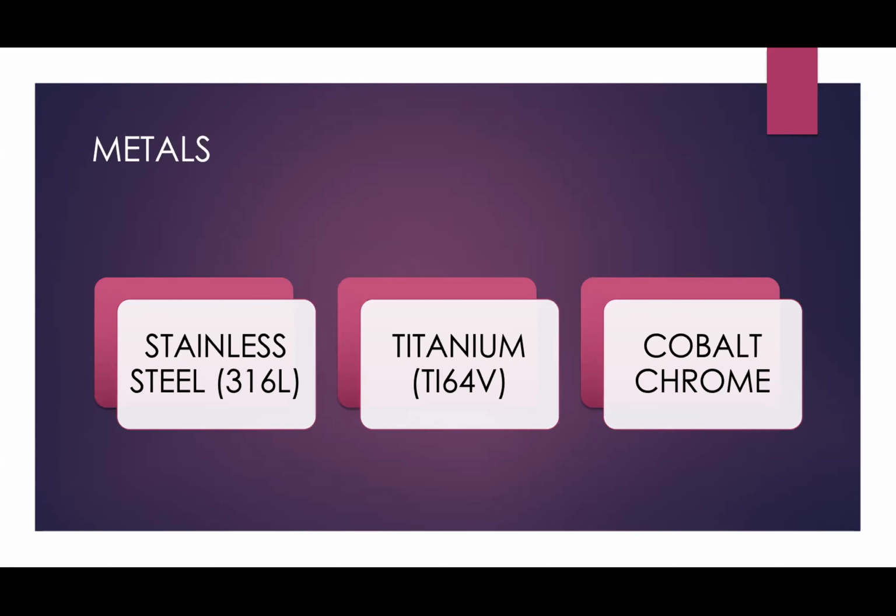It's biocompatible, but the downside is it's very sensitive to notches. It's got terrible notch sensitivity properties, which means if you sustain a crack, it will wear away very quickly. It's got terrible wear properties, so it's not good as a bearing surface, and it also gives off vanadium particles if it does wear, which can be cytotoxic. So it's used as a stem, a nail, anything for load sharing, but also some plates as well, because it's quite ductile, particularly for pelvic plates.